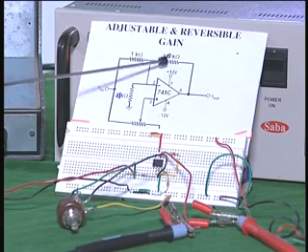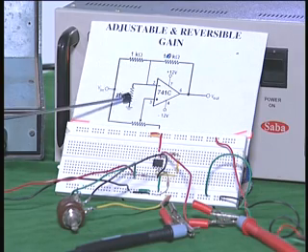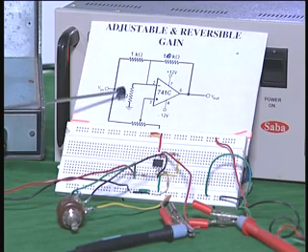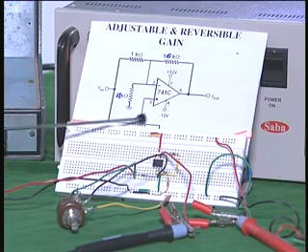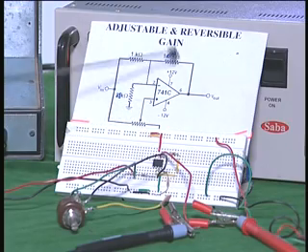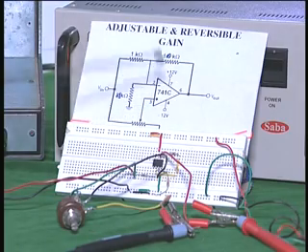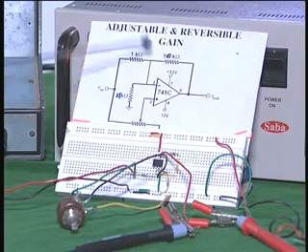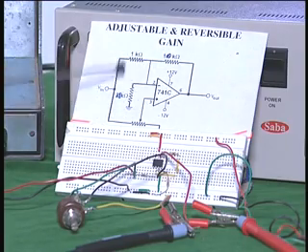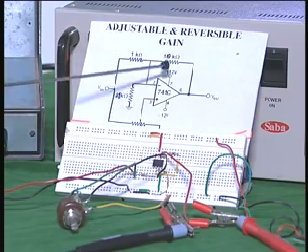For example, I can put here 50 kilo ohms, and then I can have this nearly 1k. There is no need to vary this, and then you would find that by changing the potentiometer I will be able to vary the gain of the amplifier from plus 50 to minus 50 continuously using the potentiometer. So you can put different resistors, and it is very simple. There is nothing complicated involved here.